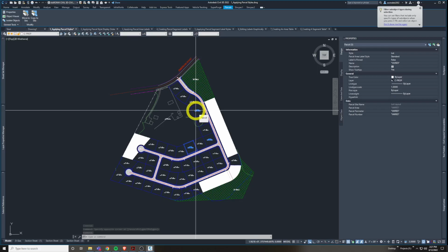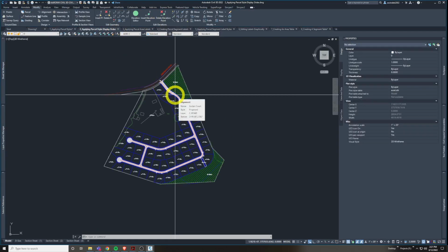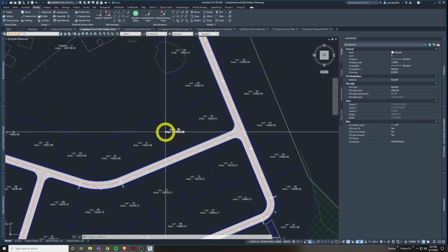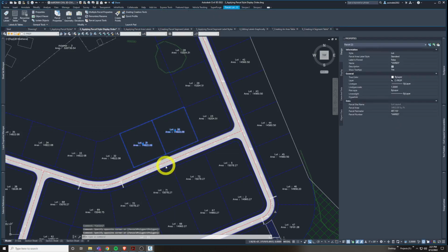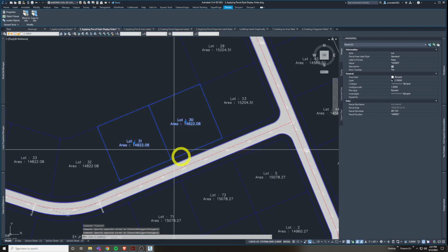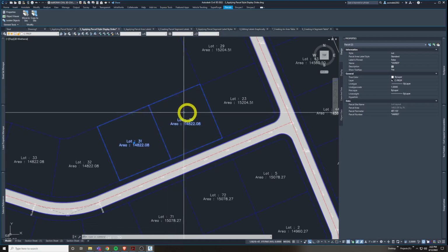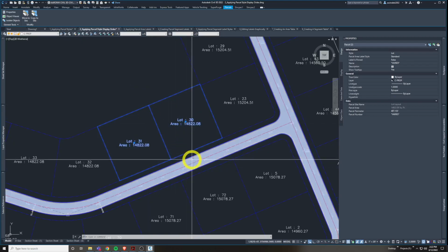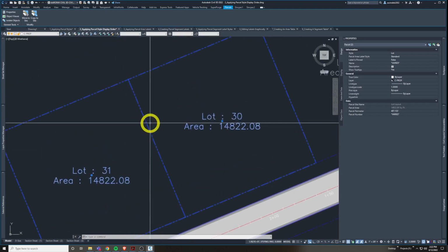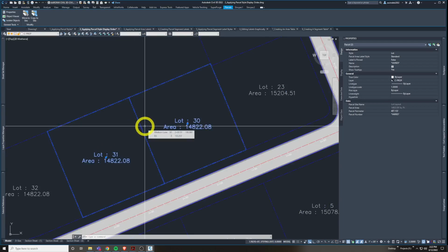Let's go to 256, talking about parcel style display order. I'm going to move to the next drawing. So oftentimes, this is interesting enough, if you make parcels touching each other adjacently like this, they generally share multiple boundaries, or possibly just one. In this case, they share this adjacent boundary. So one thing with parcel styles is you can tell the style which one to display first or last, depending on which symbology you want to be dominant in their shared boundaries. That's a critical piece if you're going to build these with the parcel manager.